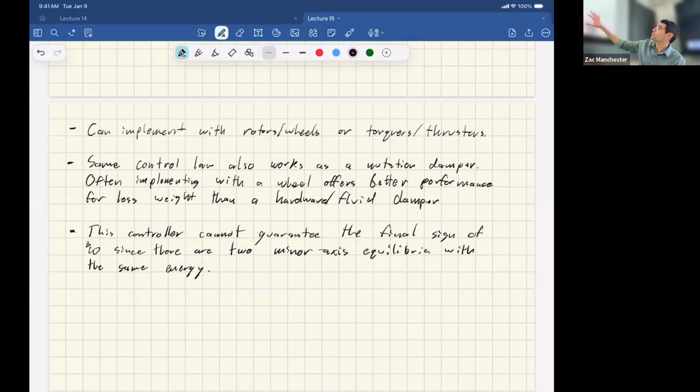And then here's the really fun one that doesn't happen with the nominal controller that we just wrote down. This gets you this spin inversion behavior where if I'm spinning the wrong way, it'll actually wind me out and then flip and wind me back towards the North Pole. So it gets you all the things you want. That's what it looks like. Kind of cool. So you can fix the classic with some tricks. That's what Lyapunov stability looks like. Kind of fun.